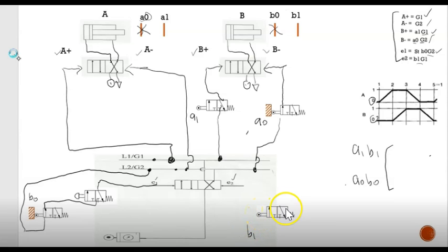Since this is the normal limit switch, we are going to use this one, so E2 will be connected here. From here we connect to G1. Oh, sorry, G1 is upper here. Don't forget the loops. G1 is here, so make sure you don't cross it straight. You have to do the loop.